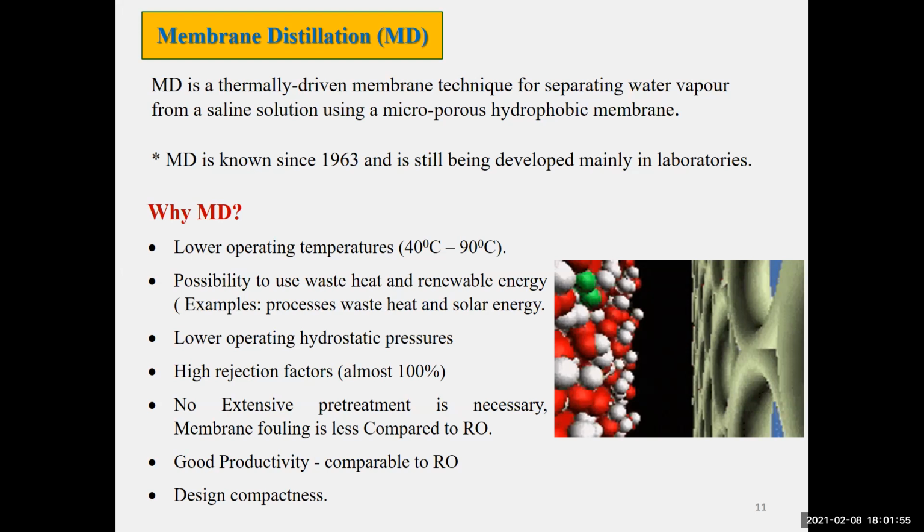But for membrane distillation, no. On the hot side, you are just passing hot water parallel to the membrane. It does not penetrate the membrane. You are not pushing water molecules inside pores. Actually, the pores allow the vapor to move.